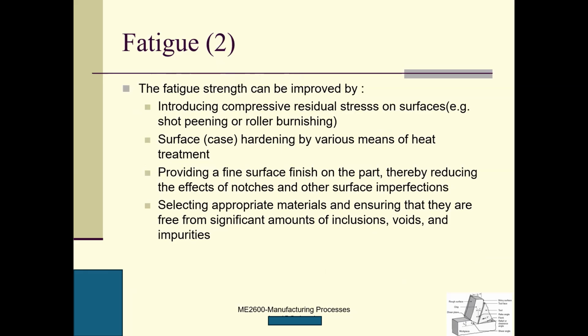Okay. My fatigue strength can be improved by the following means. First, introducing compressive residual stress on surfaces, which is what I told you, right? If you induce compressive residual stress on the surface, you are increasing the fatigue life of the component. Why? Because compressive residual stress prevents cracks from initiating and propagating.